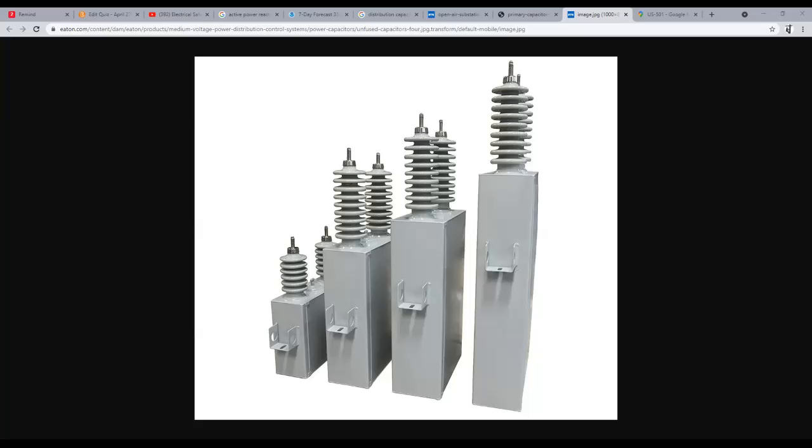Hey, I got a question. You know how they use SCADA to monitor the substations and the capacitors we were just looking at? Do they also have a radio signal to monitor the power lines, or do you have to check those manually? If you want readings at a specific location, you have to do that manually. If you want the reading for the entire circuit, that is done at the voltage regulator at the substation.